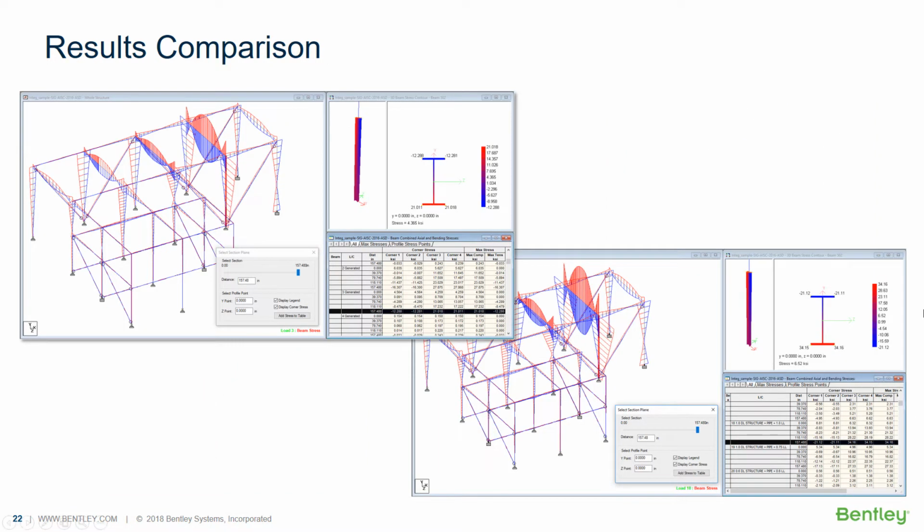So what we see is that we had at one point, when we were just looking at structure, a stress on beam 502 of 4.365 KSI, and now on that beam 502 again, with the piping and structure both being considered, we're looking at a stress of 6.52 KSI.